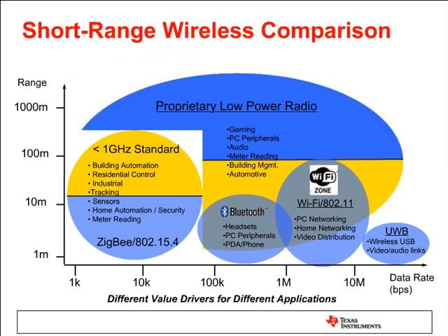And this does have some implications on the different wireless applications or the different networking protocols that you can apply. So as it stands today, TI's Zigbee solutions and in fact the modulation that you have inherent to the radio and everything separates what we call the 802.15.4 protocols, which does include Zigbee, or just 802.15.4, is separate from the CC430. What you'll tend to see is that many companies in the sub 1 gigahertz space have either their own standards or they've developed other industry standards.